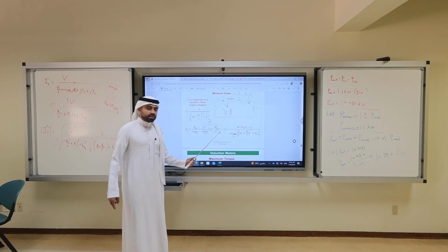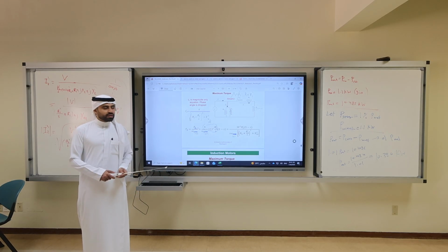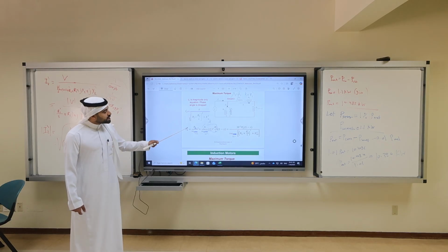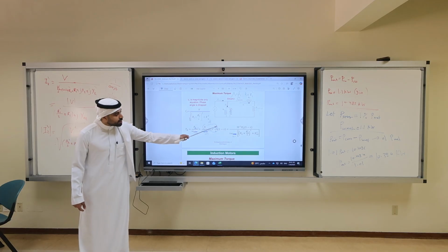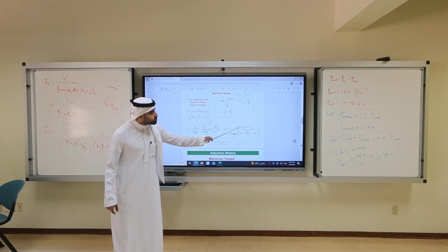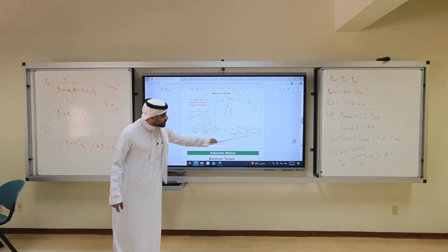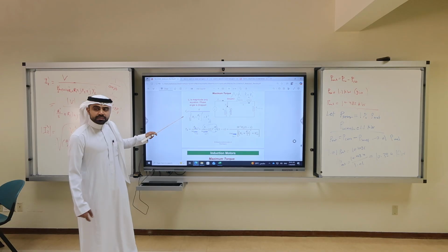Okay. So I will fix it. Take a photo and remind me to fix the slides next time. Okay? It's easy to fix. Torque is P converted over omega M. P converted is PG times 1 minus S over omega M, equal 3V2 square R2 prime (1 minus S) over S omega M plus this bad ugly expression.